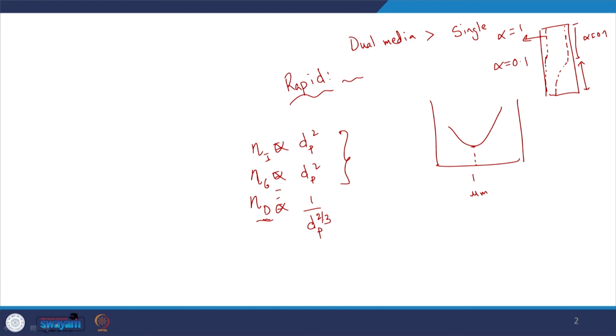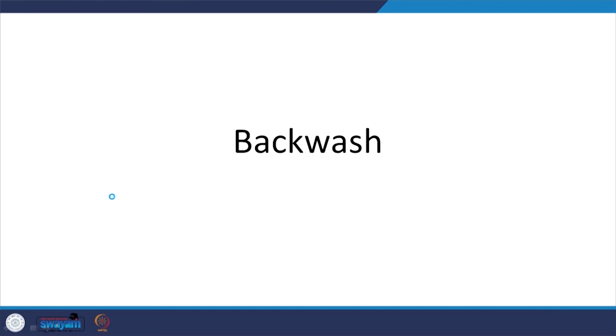We also saw that head loss will increase over time of operation. For head loss, depending on whether it was laminar or Forchheimer flow, with Reynolds number between 1 to 100, we have different equations. Within that we also have equations for spherical and non-spherical particles, and to take that into account we have the shape factor. So, these were the aspects we looked at in the last session, and we were about to look at the design aspects with respect to the head loss, right.